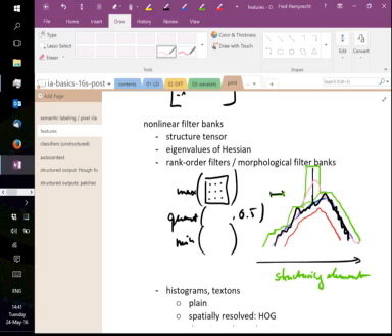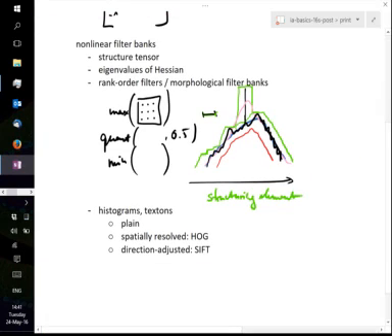That's an attractive property. So why did I spend so many weeks talking about linear filters? And why do I only talk about these fleetingly? An important reason is that these rank order filters are so much harder to characterize. For the linear filters, we saw that just knowing the impulse response, or equivalently, just knowing the transfer function, tells me everything I can possibly want to know about that filter. But with these rank order filters, it is much harder to characterize them in a data-independent fashion.